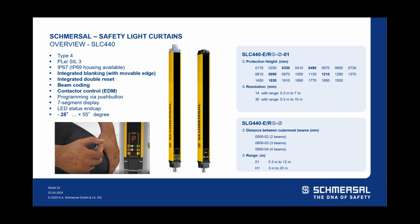Again, you still get your end cap, so you get that visual from across the plant. I can't tell you how many times people have said that saved them downtime. Somebody maybe not meaning to had broken the beams or interrupted the light curtain and walked away, and somebody saw that it was red and was able to go and reset the system. Now you get that 7-segment display where you see that P for programming. It's going to give you alignment aid and some error statuses that you can use for troubleshooting. So again, the 440 has a ton that comes already programmed in it. On the right-hand side, we see the different protection heights and resolutions for the SLC. And then we see the range and the distance between the top and bottom beams for the safety light grid.